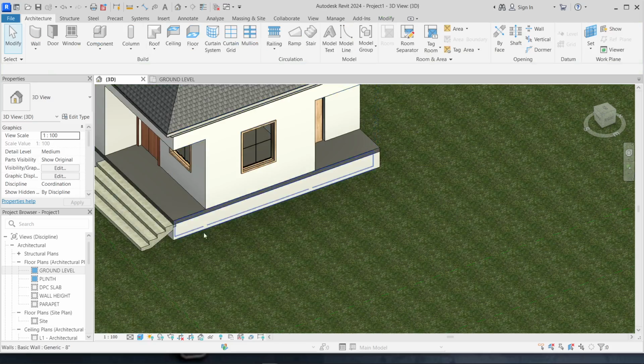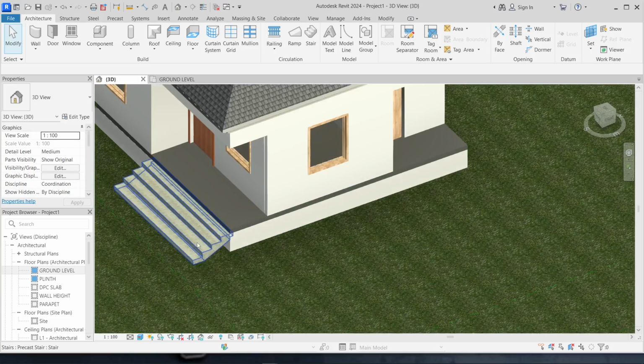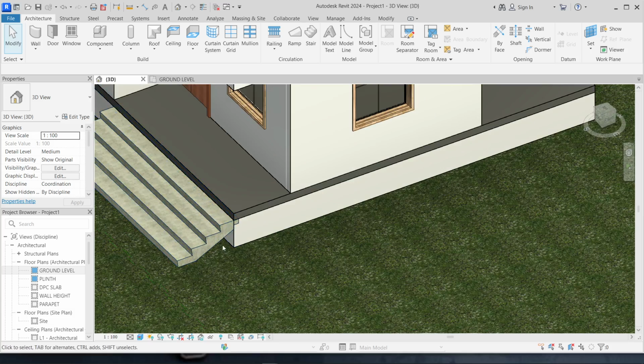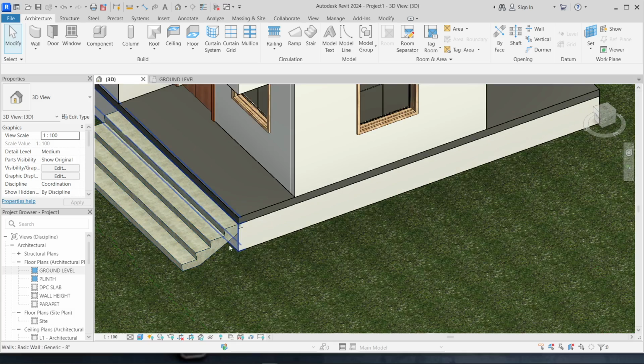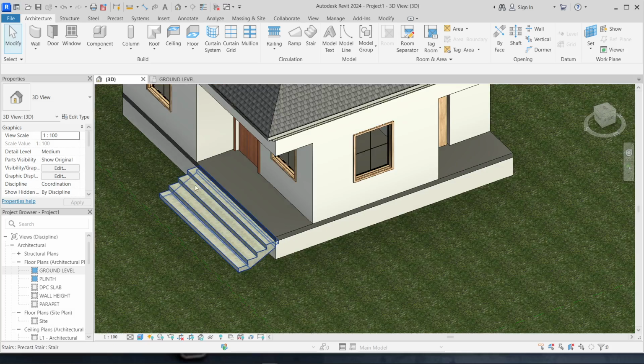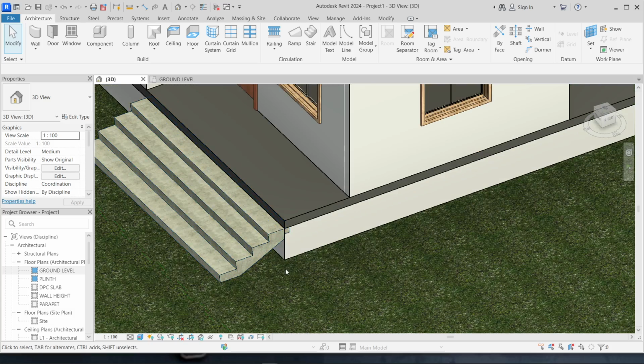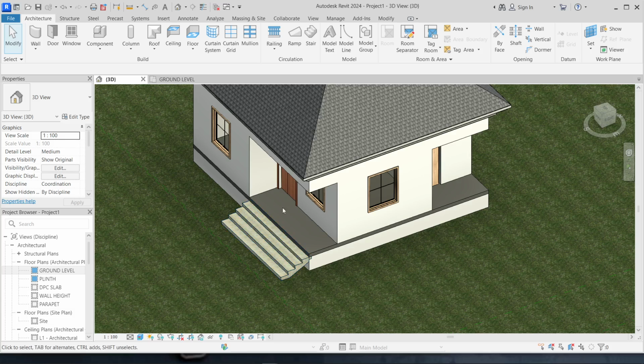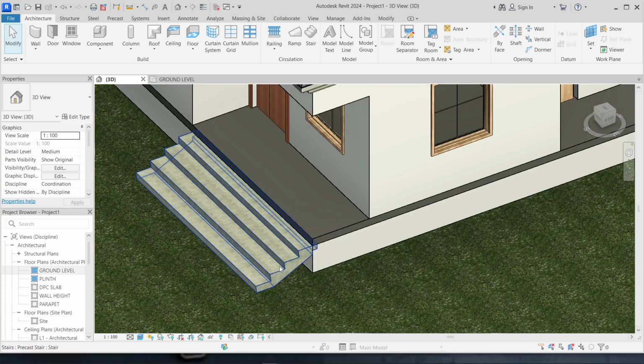So now I want to show you guys another way you can use your slab and put a staircase. The reason why I don't like using this staircase, you see that we have a hole right here, which if you leave this, it's not okay to have something like this in your building. Any reptiles or something can actually go inside there and hide, which any human cannot access. It's very dangerous and very hidden, in a way that things can hide there. So you have to make your staircase not hang this way.